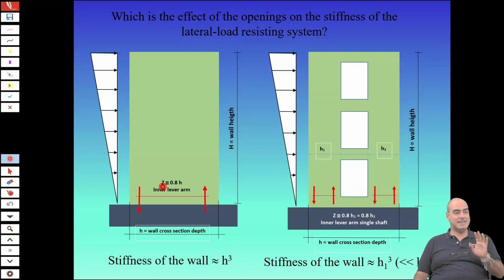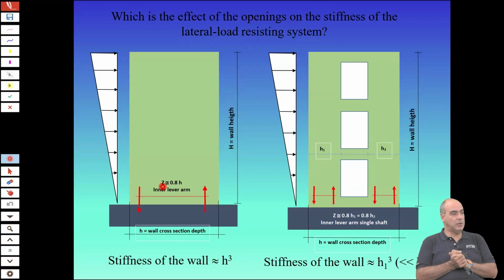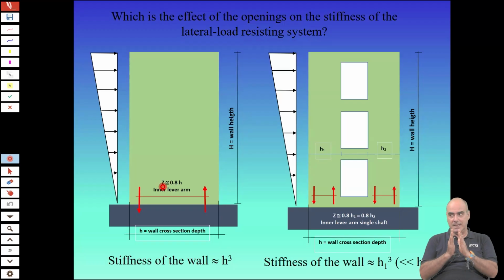If you are on a 60-meter building, 60 meters is a medium height building, what is 1 per mil, 0.1% of 60 meters? It's 6 centimeters. So you will still start feeling this. But if you go for a very high rise building, 200 meters, 300 meters, 400 meters, it means 40, 30 centimeters, one way and the other way.